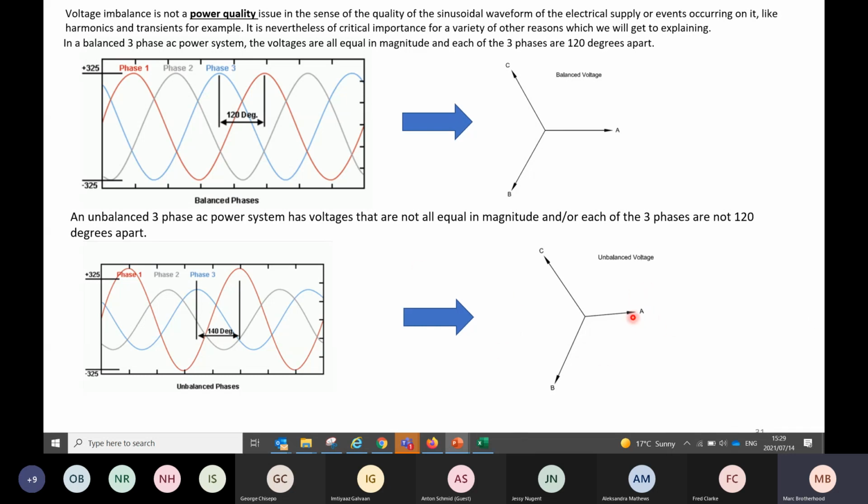This is a lot easier to understand than all this fancy stuff, but this is a vectorial explanation. Now we see, whoa, C and B are pulling a lot more current. A says had a voltage drop, and if I put a protractor here, I see there's about a 5-degree angle. Whoa, everything's going out of phase now. Okay, bang, bang, jeepers, and this is starting to mess with my whole supply system.